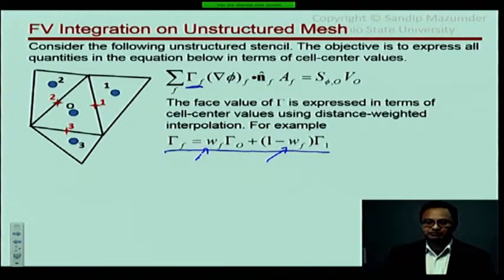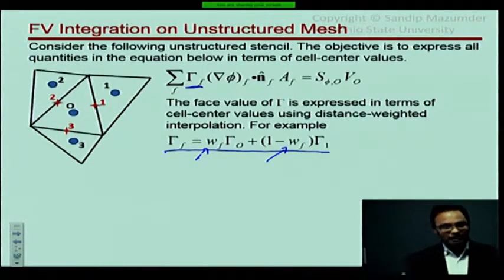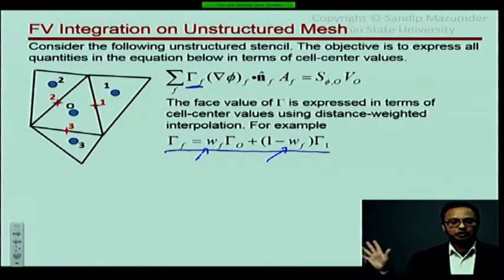So suppose you want to assemble your matrix for the finite volume method. You've done all the grid processing, all the geometric processing. Then probably the next step would be to call a function which will calculate gamma f for each face, because I'm going to need that in the finite volume formulation. Rather than do it locally on the fly, I'm just going to calculate it in a function and store it, so I can just use it later on. So that's what you would do.